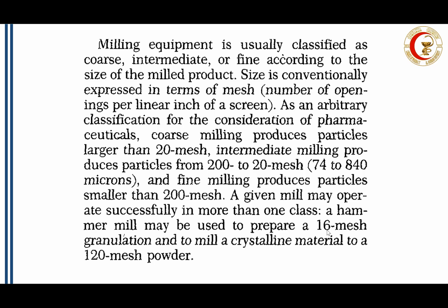For coarse milling, usually the particles are larger than 20 mesh size. For intermediate milling, we have from 200 to 20 mesh size, that is 74 to 840 microns. And fine milling produces particles smaller than 200 mesh.